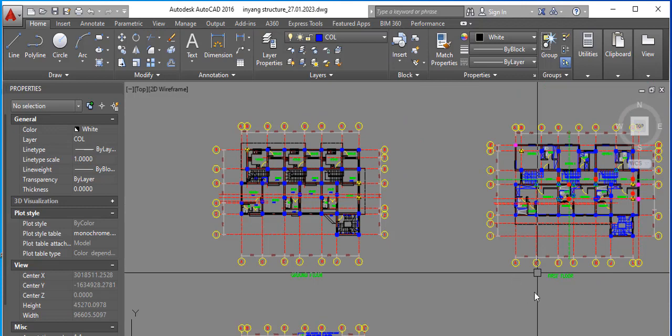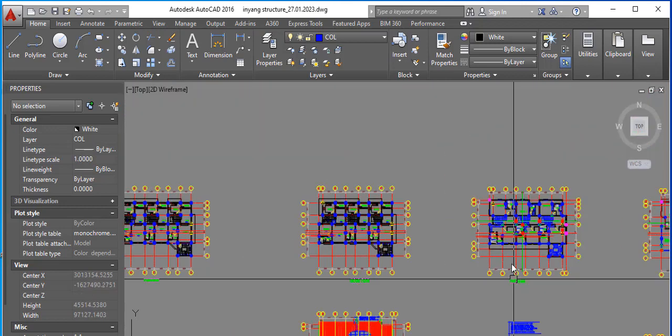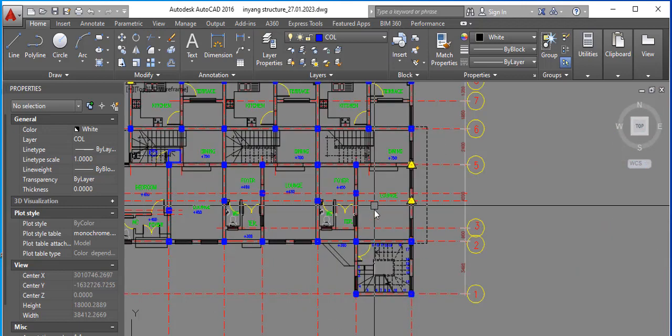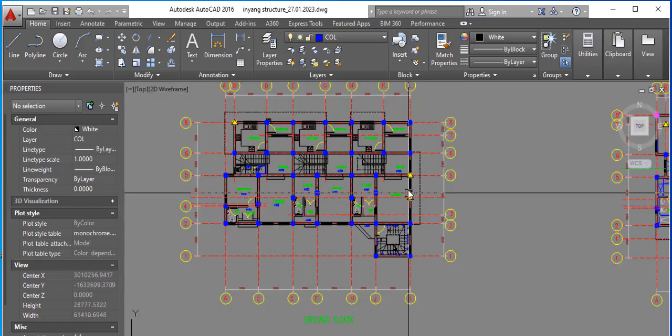So coming to your first floor, please pay attention. This is very tricky. Between your first floor and your ground floor, you have to position your beams inside the walls in the ground floor, so that when you are on the ground floor looking upward, you won't really see the beams coming out.